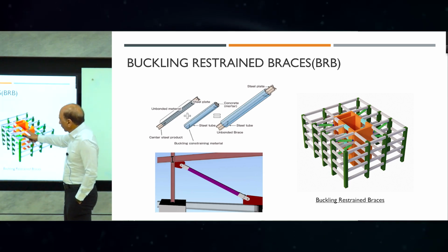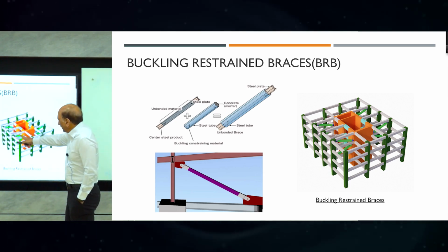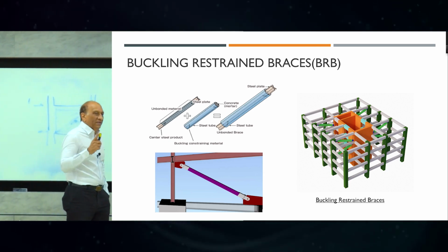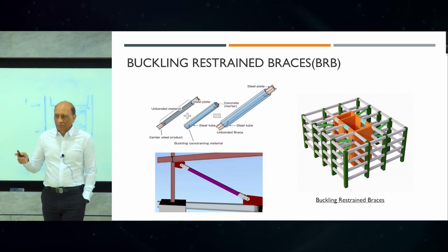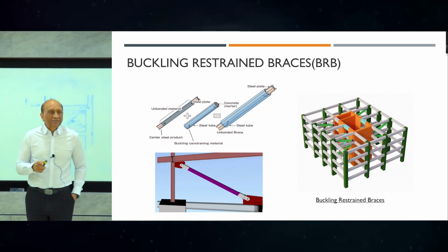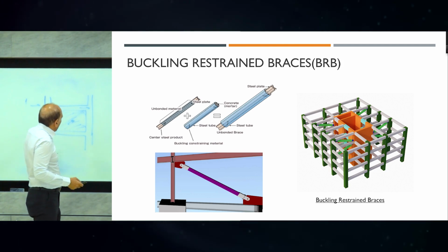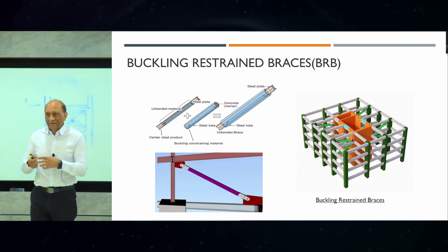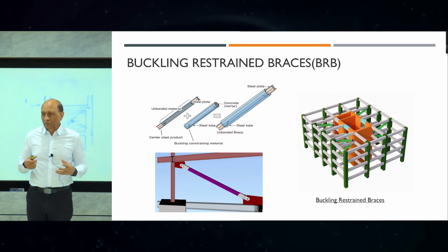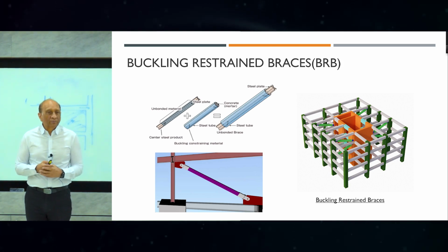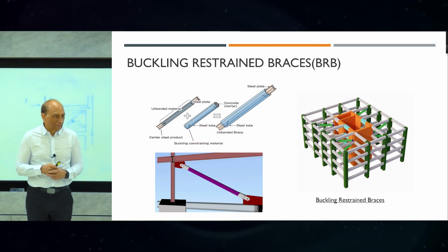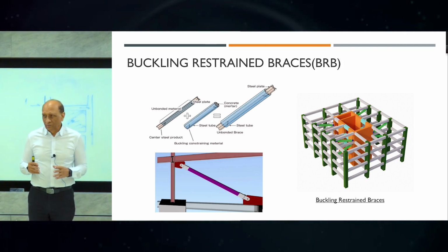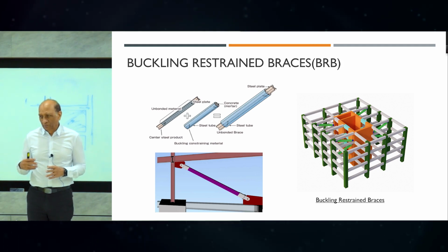And for tall buildings, we use the BRBs. I mentioned to you before, buckling restraint braces, because braces are not good. We will talk more about that. But basically, braces attract a lot of force. When you move it, it will get a lot of force, and then it adds a lot of stiffness, but it will buckle. It doesn't have a good ductility. So we don't want ordinary braces in tall buildings, especially for earthquake. For wind is no problem. England, no issue. Philippines, no, right?